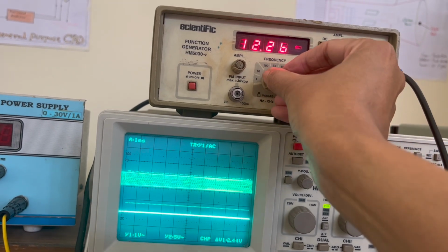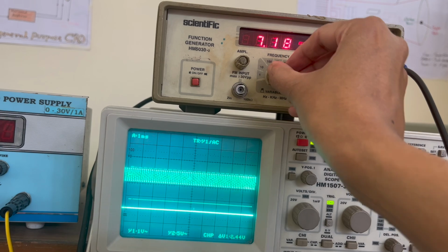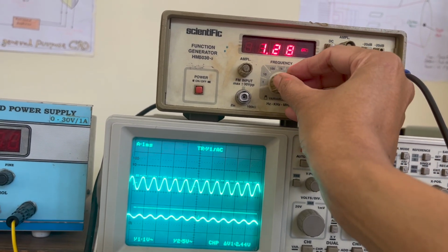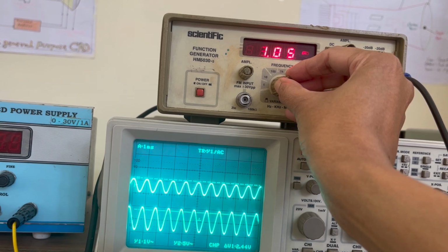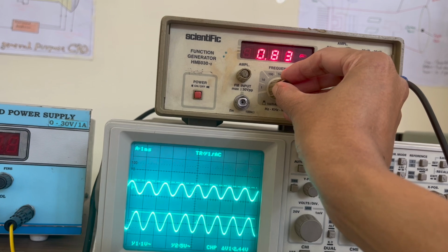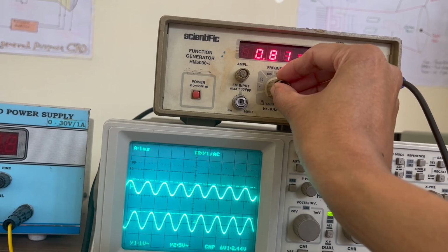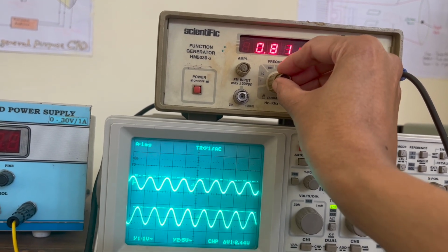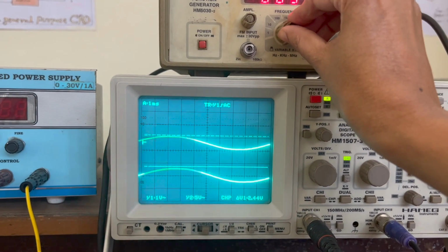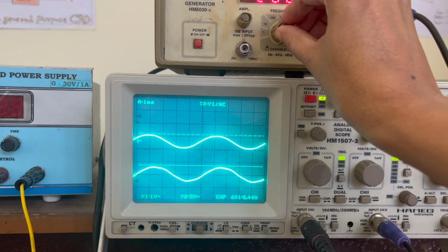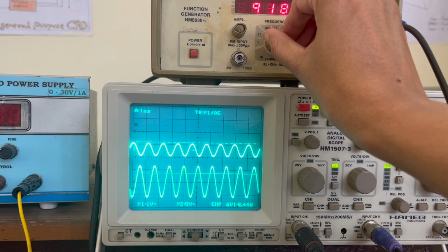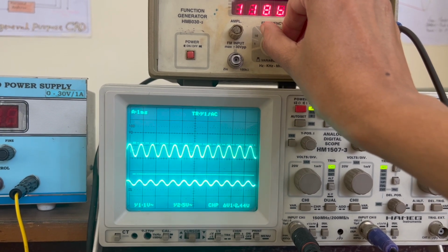It is a low pass filter. At 12 kilohertz, no output. Reducing it to 3, 2, 1, 1 kilohertz, and it increases. This is the ripple and it decreases again, right. So, we observed the ripple in the Chebyshev filter. If we go a little further, we can observe one more ripple here. It will slightly increase, and see, it will decrease, right.